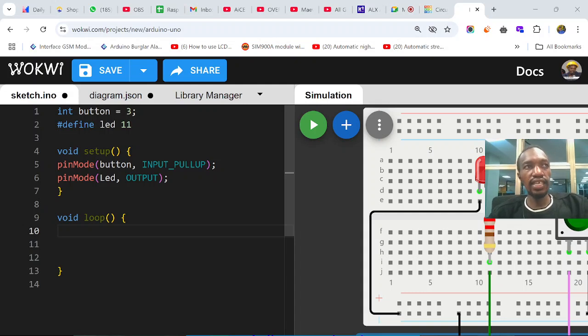If you are using a sensor, let's say if the temperature is above 20 degrees Celsius, the stepper motor should spin 3 times, and maybe the temperature will never get to more than 20 degrees Celsius. So your code will seem to be not correct, but it's correct, it's a logical error. The syntax is structured well, everything is okay, but it will not work.